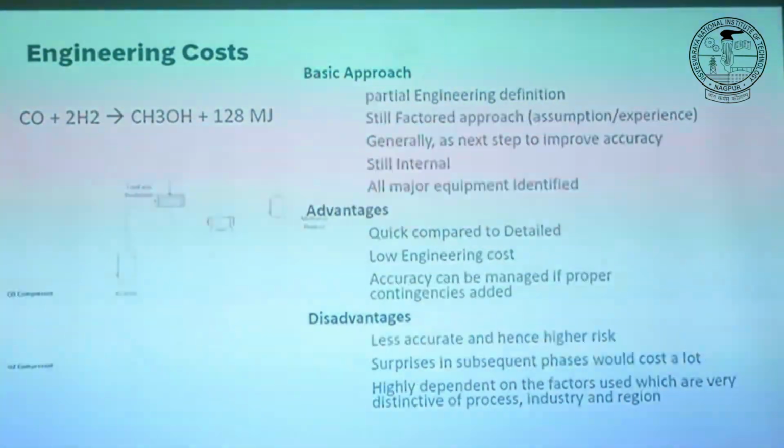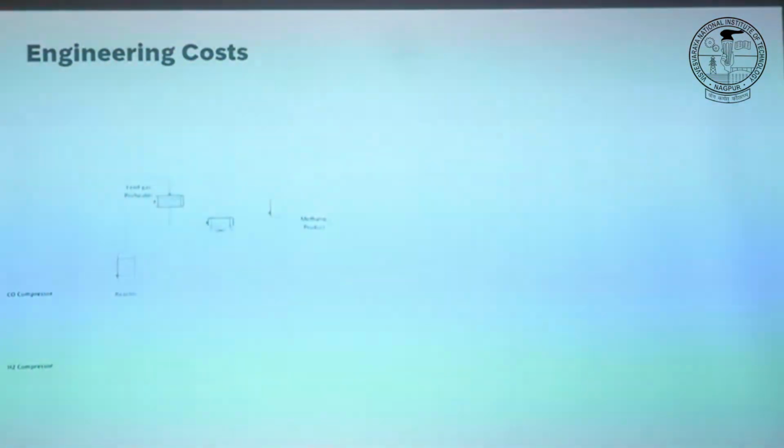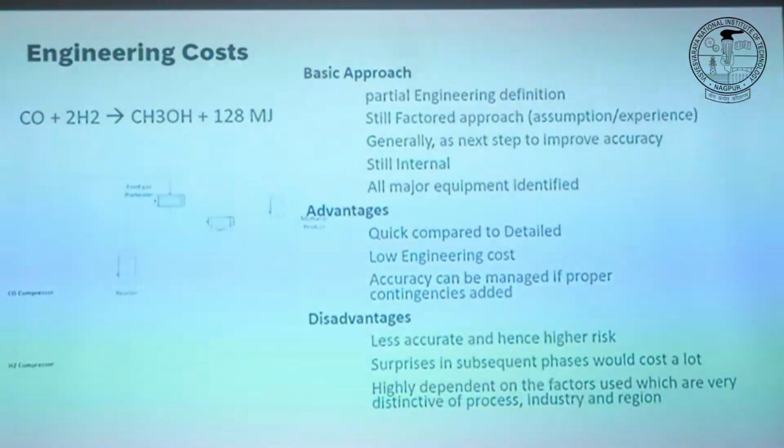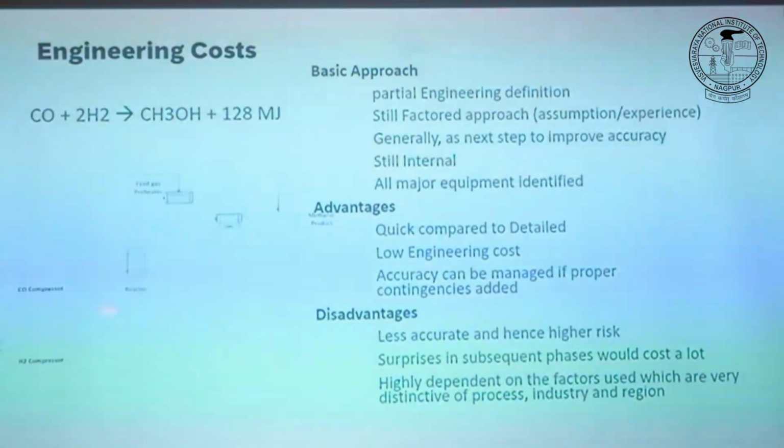Okay, let's move from this step to this step. Here we had only this reactor, two reactants coming in, product coming out. Then just before lunch, we discussed that we installed a cooling system, we installed some PICs. And it's an exothermic reaction, so we became a little bit more intelligent and said the hot reactant can heat up the feed. So a feed-effluent heat exchanger, some heat integration we did.